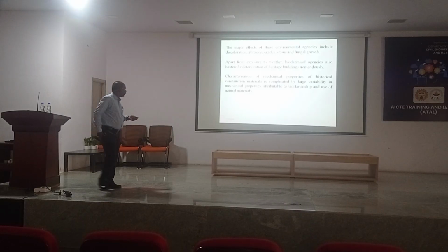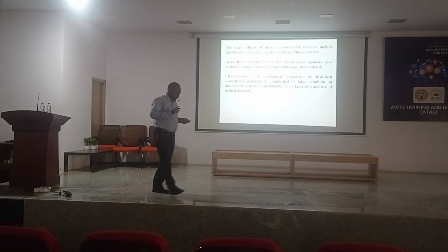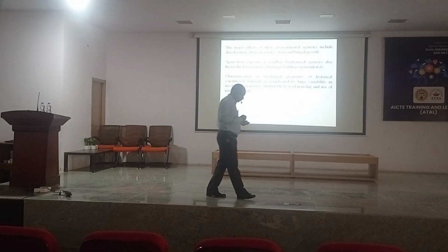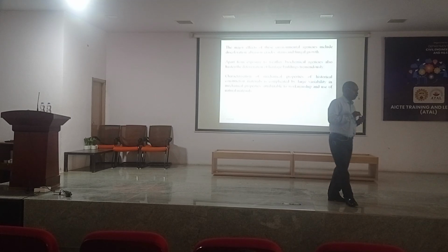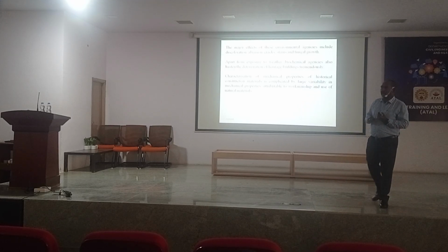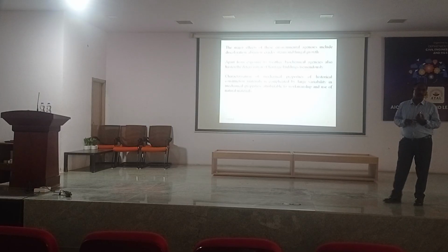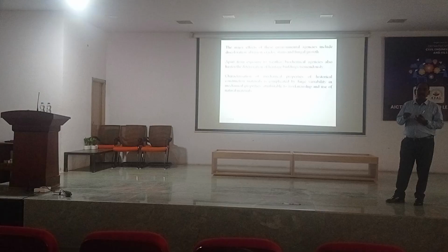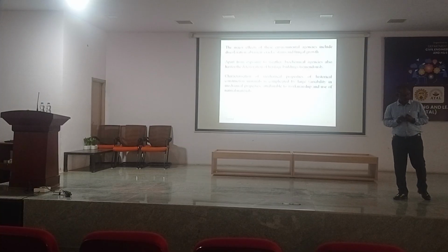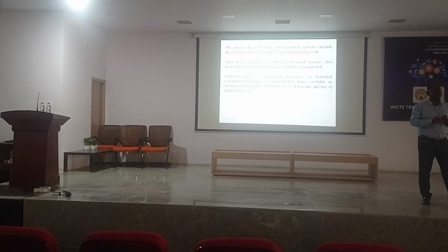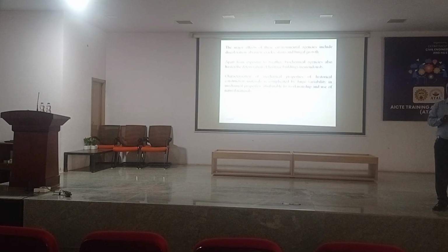Okay, for example, if you want to take up the repair of a historical structure, you can select the material from that site and characterize it by conducting various tests like XRD and SEM, to identify what materials are in the existing mortar. Then you can prepare a similar material and test whether it is suitable or not. Selection of repair material is very, very important.